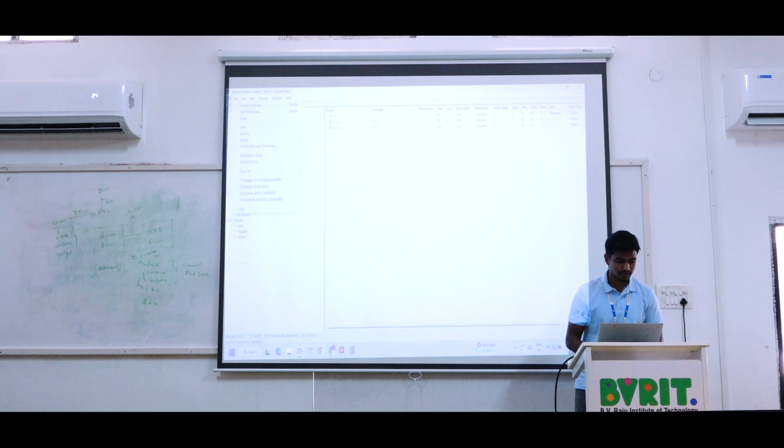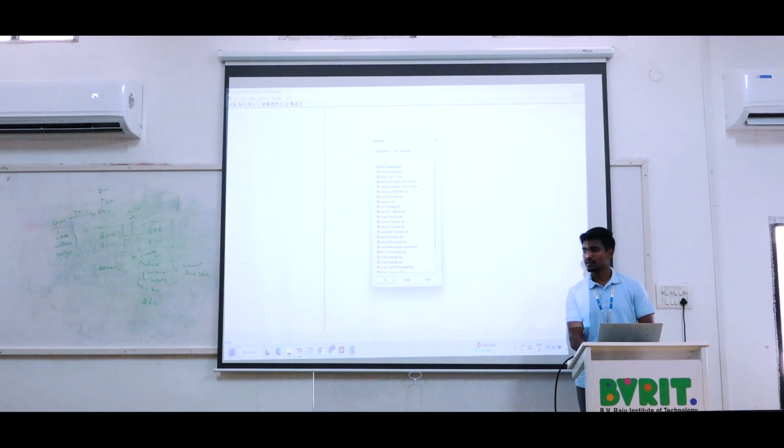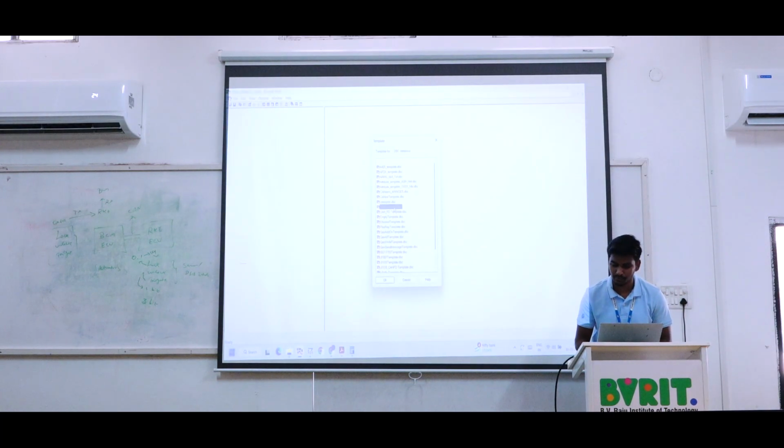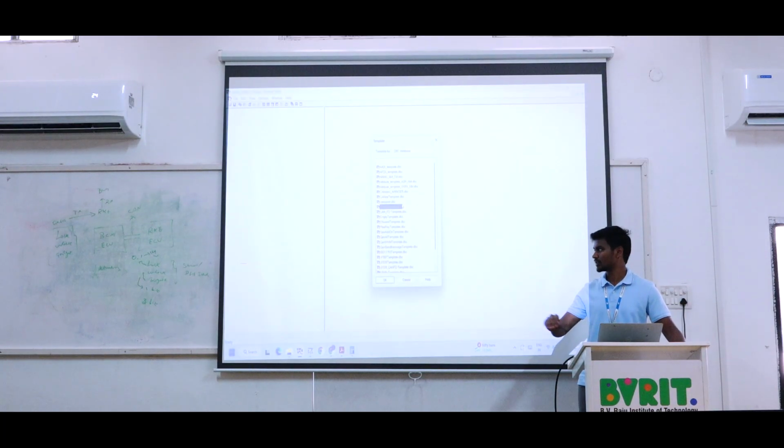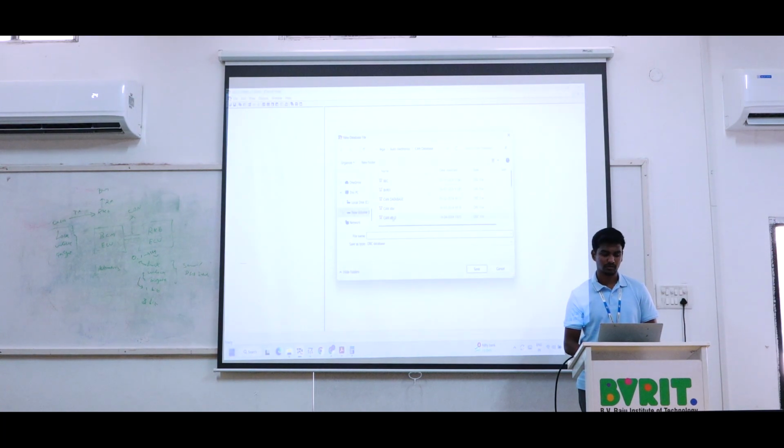So create database. I will explain the initial step. Create database, and you can select the CAN template.dbc. Please note this down, because I don't have any reference document for this, not like step by step. So I will go slowly here. Initially, give create database and then select CAN template.dbc, not FD. Afterwards give OK and then you can create the file name and path location.